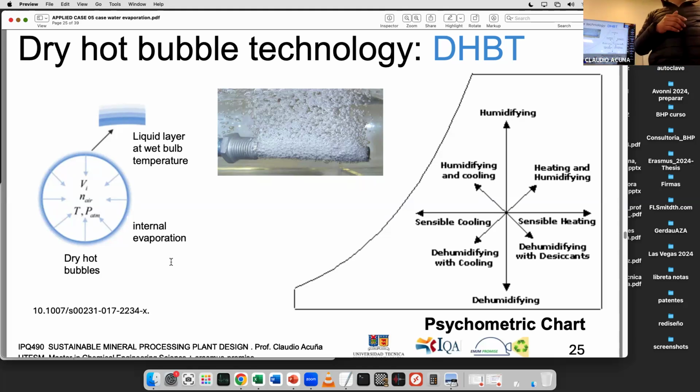Okay. Is that bubble injected at the bottom of the pond? It doesn't make any turbulence. No, you will see. It's a new device. Yes, you could inject it in the pond directly too, but they are too big, 50 meters. You can inject it too, and this will increase the evaporation rate, but you cannot recover the water. But it will accelerate. In the experiment we can reach 80 liters per square meter, so 10 times.